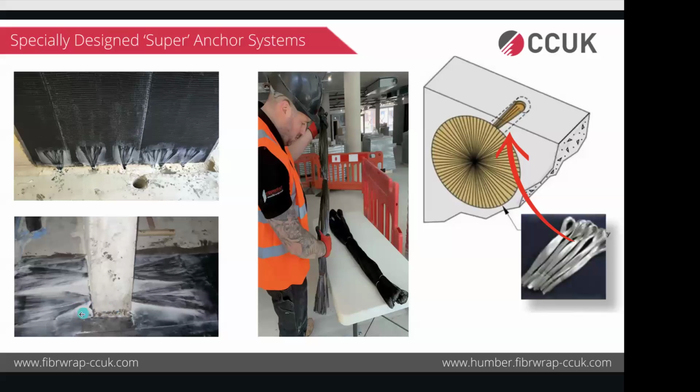Now the same thing, if you assume it tilted 90 degrees, becomes like a shear core scenario. So this is a vertical wall, and this is the slab junction. In this instance, we strengthened this 11-story shear core, and at every slab level, we used these anchors, drilled through the slab to transfer the strengthening from the floor above to the floor below. And ultimately, everything was anchored into the pile cap. So that's how you had the continuous reinforcement vertically on the wall, which is transferring back to the foundation.